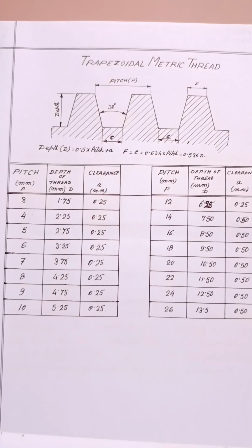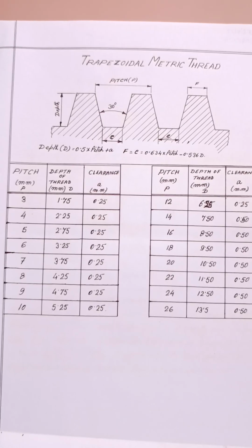And if the tool angle shifts in between, then scattered marks will be there and the job may be damaged. So when we cut ACME thread, in general we first cut rough by a square thread tool, keeping the C distance or F distance lesser than the actual size.